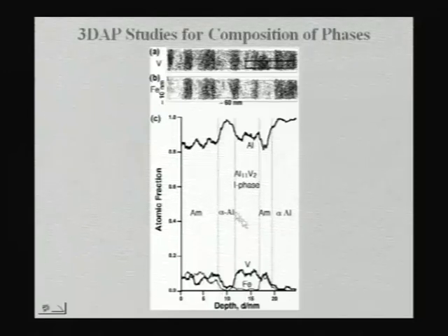domain. For example, if you look at icosahedral phase, its size is of the order of around 5 nanometers. So we are talking of such a fine nano composite consisting of amorphous phase and nano quasicrystalline phase and nano aluminum grains, and such a mixture gives you much higher properties, and that is what you see here.